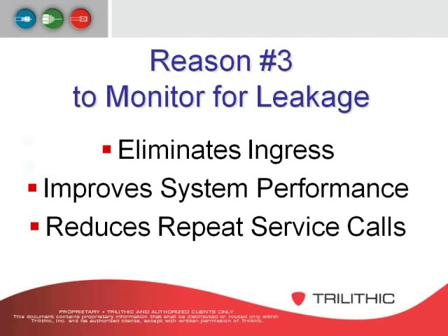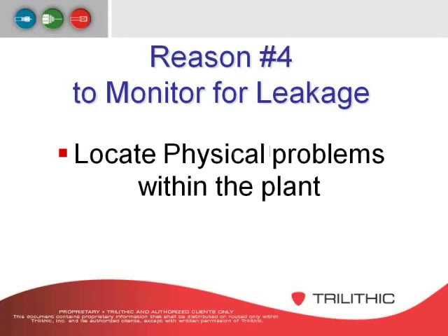So reason number 3 to monitor for leakage: it eliminates ingress. Remember I mentioned that if signals are leaking out, there's a strong chance that signals are leaking in. It improves your system performance, because when signals leak in, that can affect the carriers that are present, and it reduces repeat service calls.